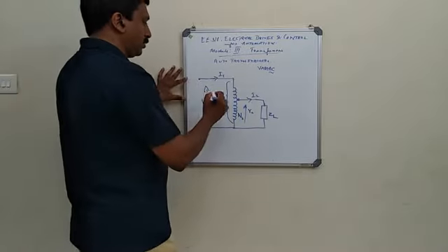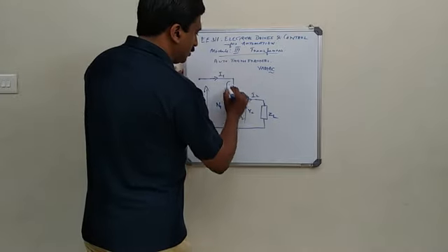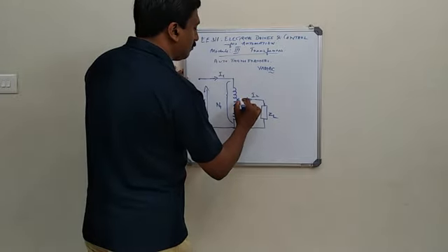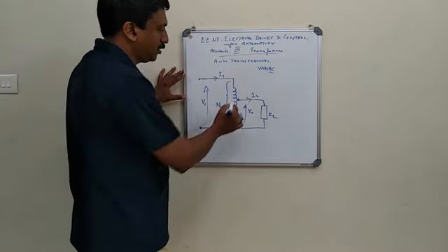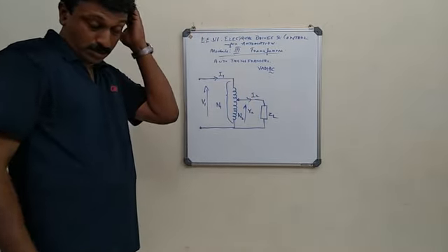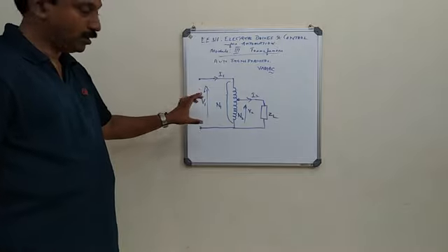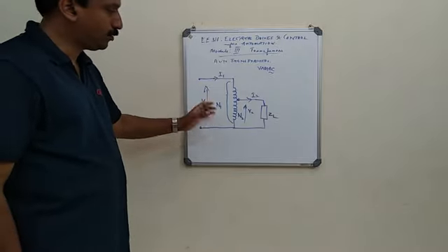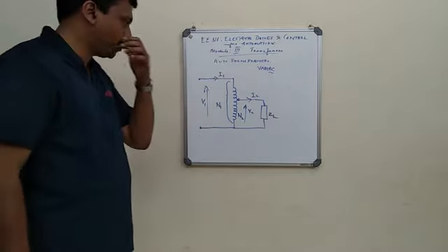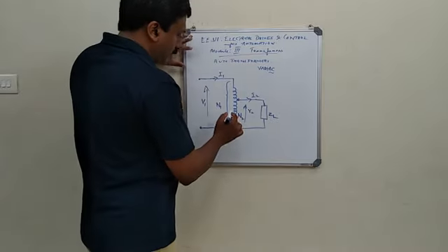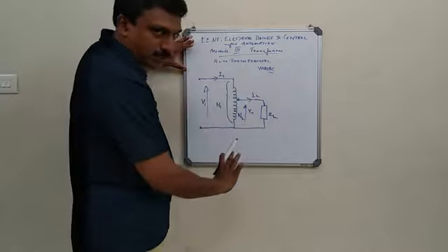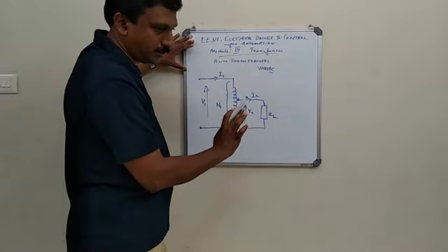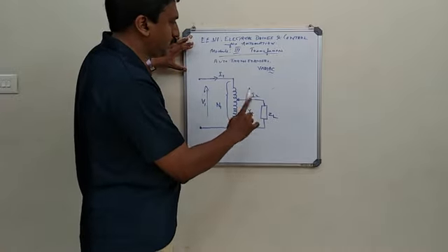So here what you can see, you have current I1 coming in and I2 going out, both indicating V1, I1 the input power, and V2, I2 the output power. Now the current through this N2 number of turns, which is a part of that N1 turn. So that is the major difference with the two-winding transformer.